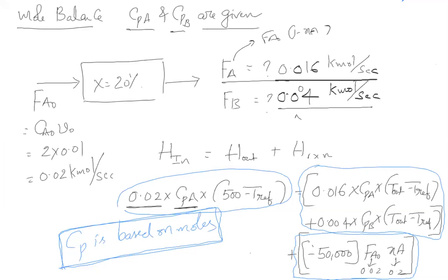So everybody understood why I have written the balance like this? Here it is very important. Yesterday, if you see, I have written just, mass-based energy balance is always extremely simple because MCp delta T is equal to MCp delta T. Clear? So here, when Cp is given in terms of moles, then the problem begins. So if everybody is done, the answer is 600 Kelvin.